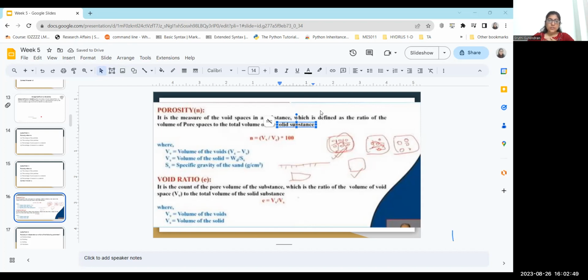Yes, Ganesh, sandstones and conglomerates are also good aquifers. But when you compare them, fractured limestones are better than sandstones. If you're comparing granites with sandstone, sandstones are aquifers; granites are not at all aquifers. But when you're comparing the aquifers in sedimentary rocks, sandstones are a little less good than limestone aquifers.